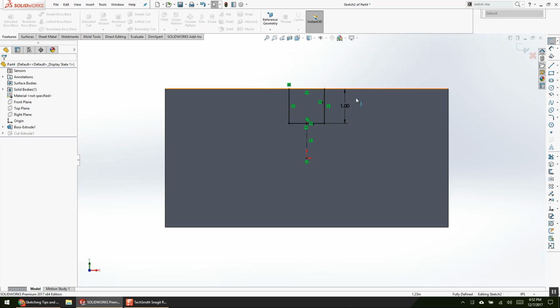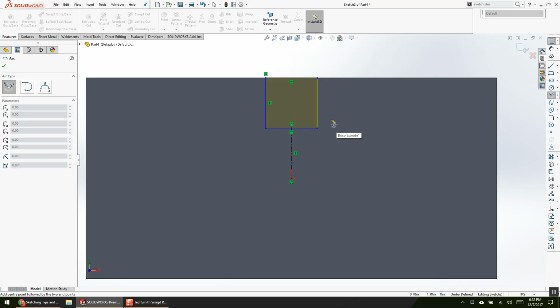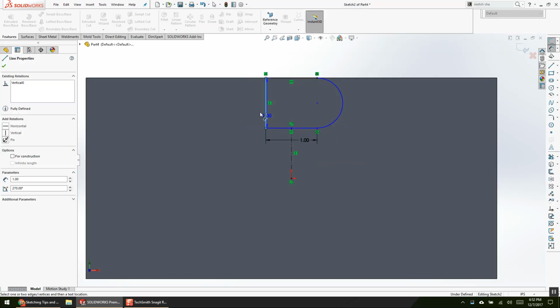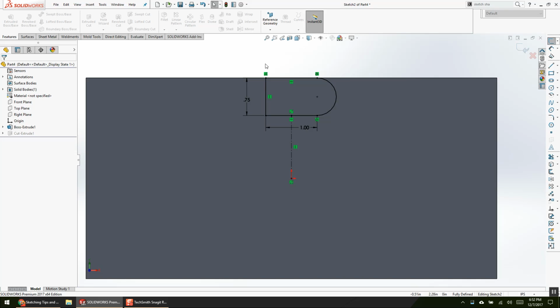The other big problem is if I do my model items and I do import my sketches, if I want to reconstruct this and I delete that because I add an arc like this, and I'm going to add another dimension there and another dimension here, and let's say that's 3/4. I just deleted the dimension that now appeared on my 2D print. So my 2D print now is going to be having a problem, versus if I did native dimension of that 2D print and the geometry persisted, I didn't now break my 2D print.